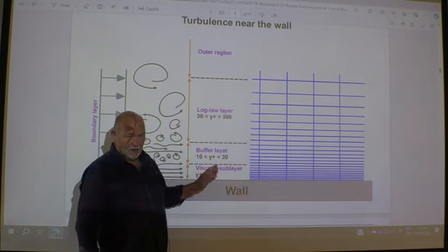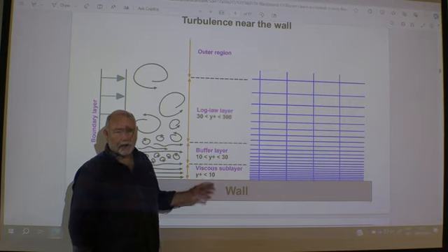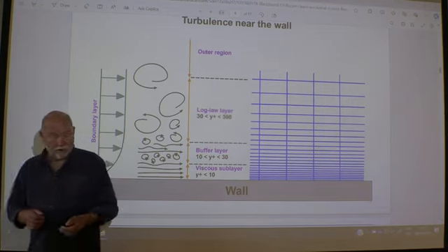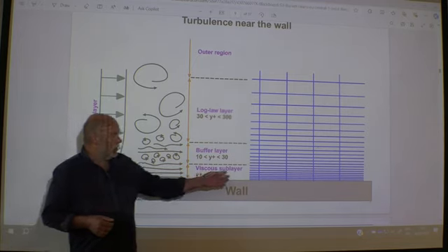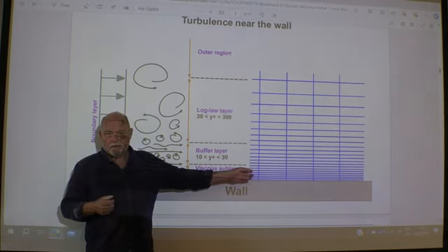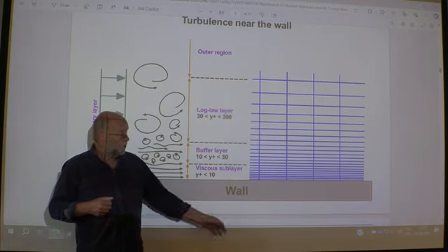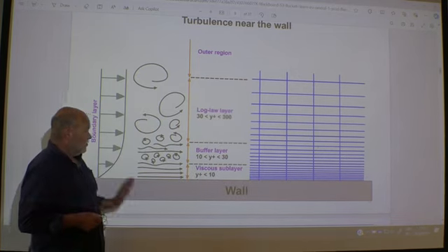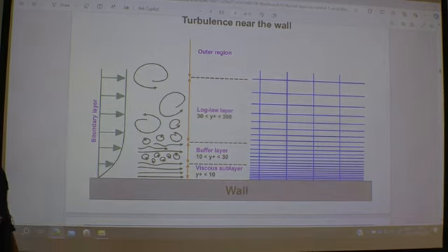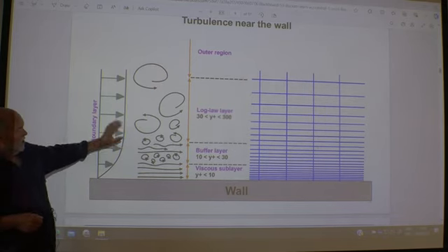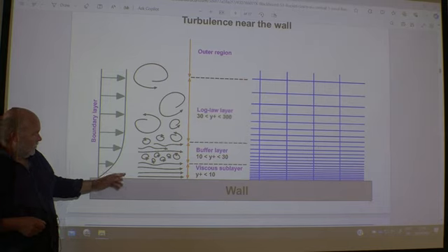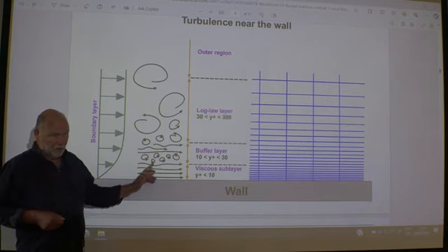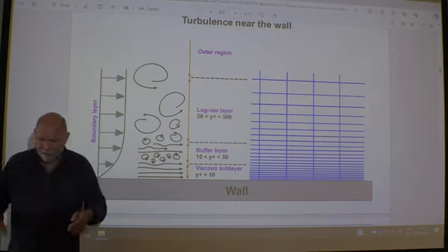So this is a good resolution of the boundary layer very close to the wall. Here you don't need any wall functions or anything like that. You have a natural boundary condition. Velocity is 0 on the wall. Done. So no problem there. The image here is not entirely true, of course, but never mind. As I said, there's actually a lot of things happening here, but we model it away.